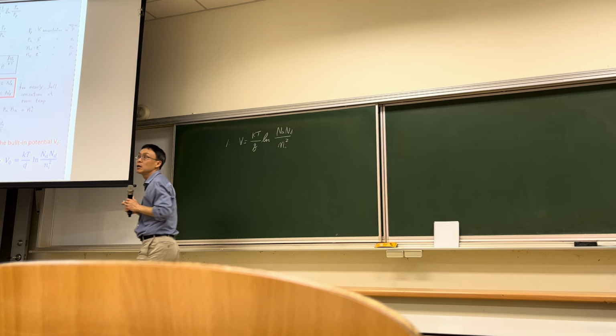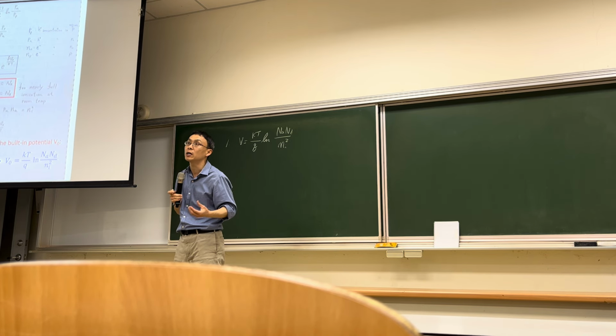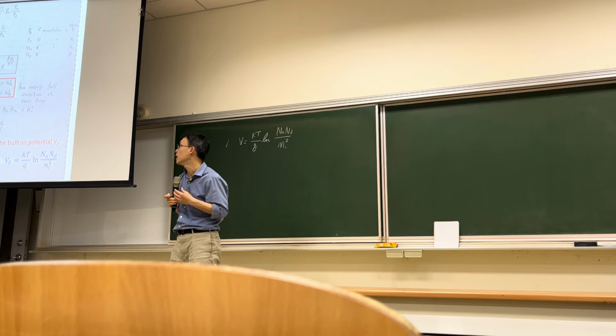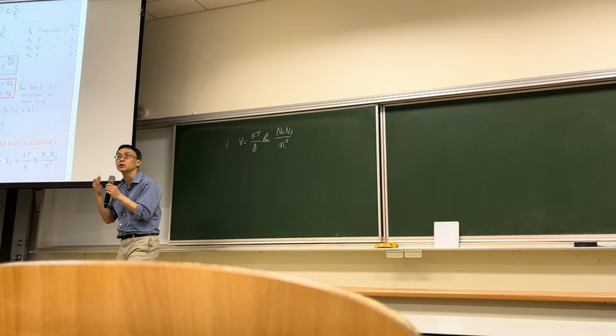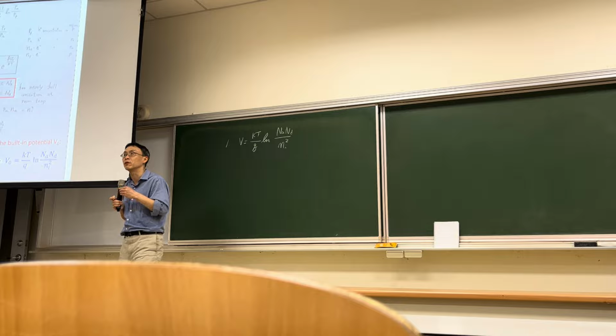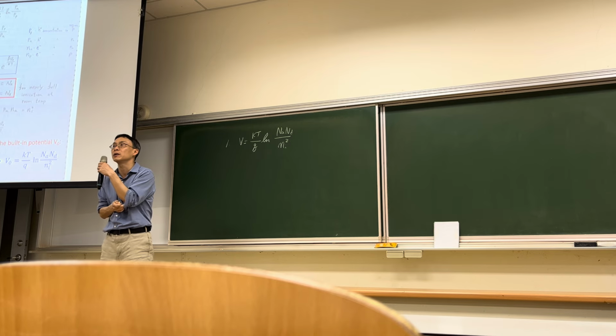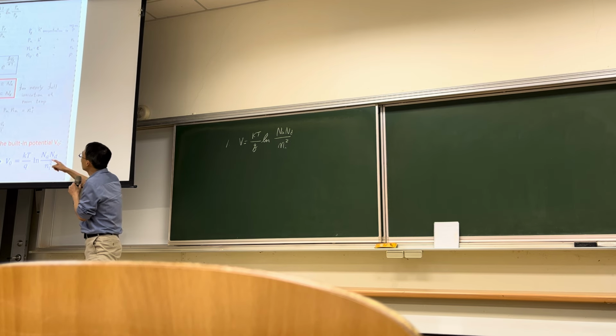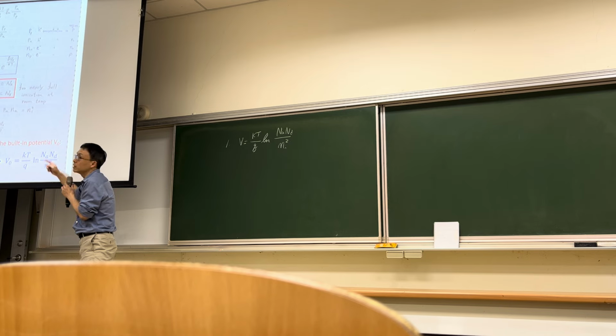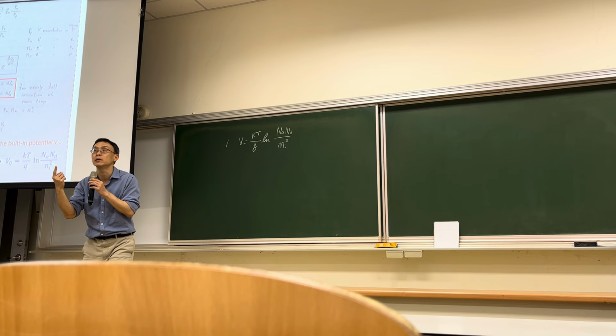So if the ionization percentage is not 100%, we need to slightly modify the final results by the percentage of activation. For example, if you only have 90% of the electrons and holes excited from the impurity level, we need to multiply the Na and Nd by 90% because that's the doping concentration.